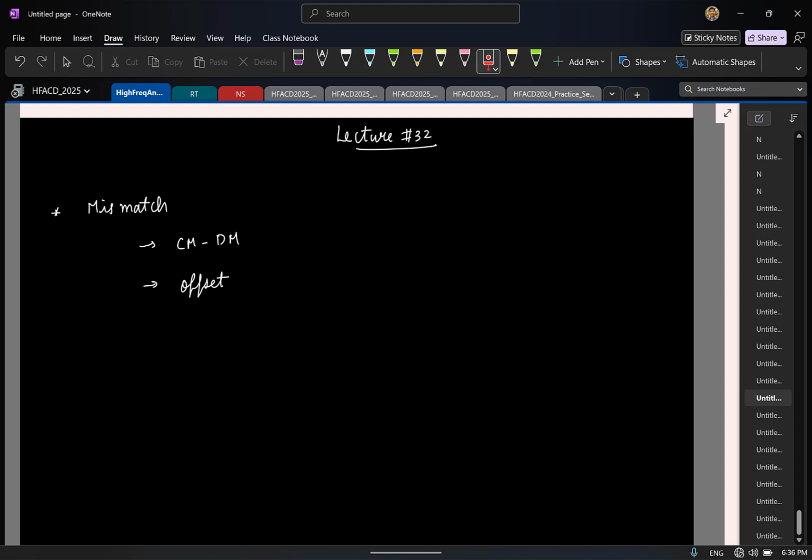Let's say you take a normal diff amp, the tail current source, right? So if you have a good tail current source, you can actually go and tackle this. So what I'm getting at is mismatch is not something really fundamental. You can come up with circuit techniques to get around the problem.